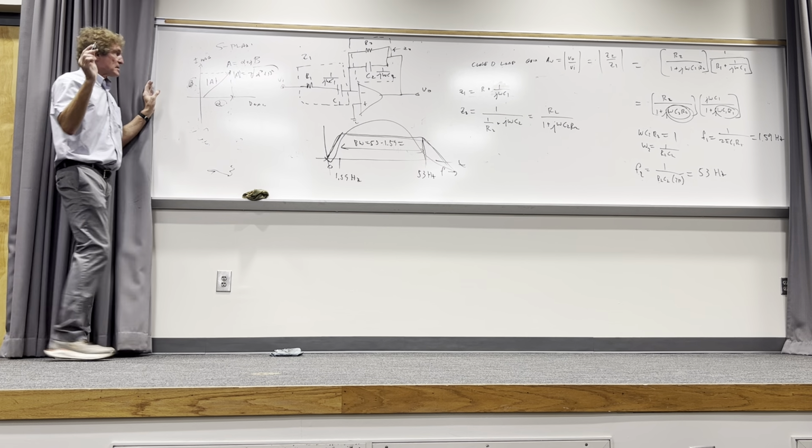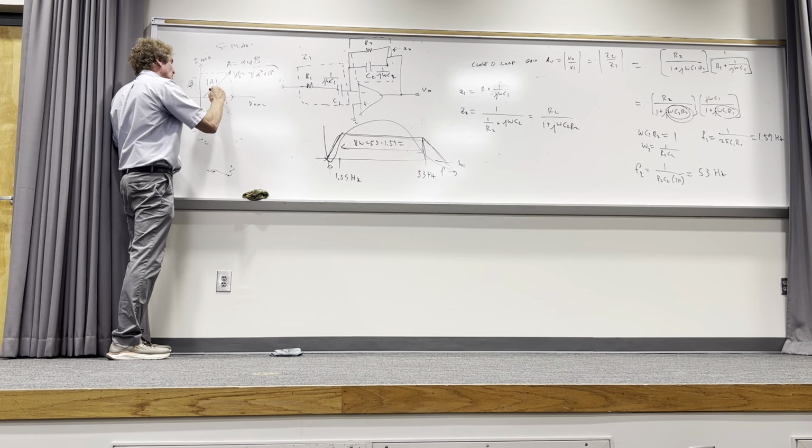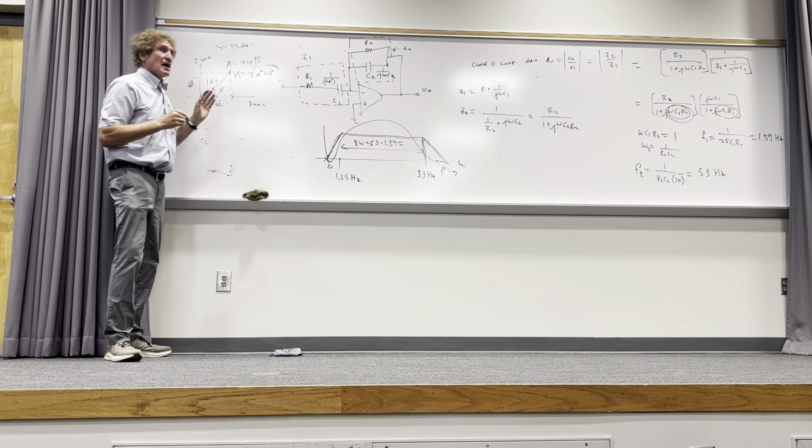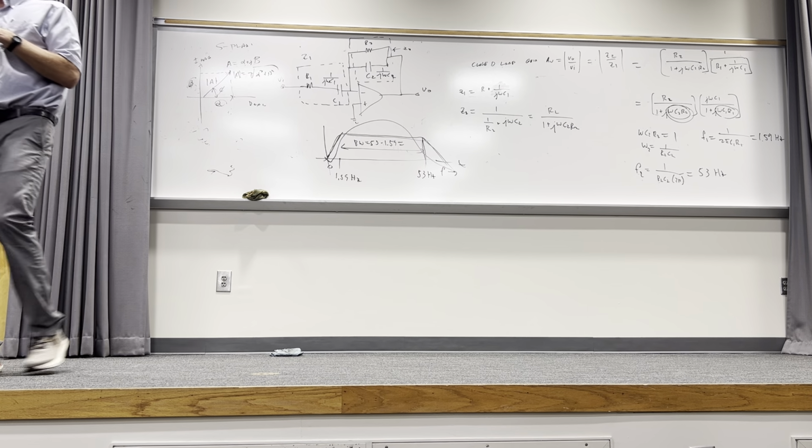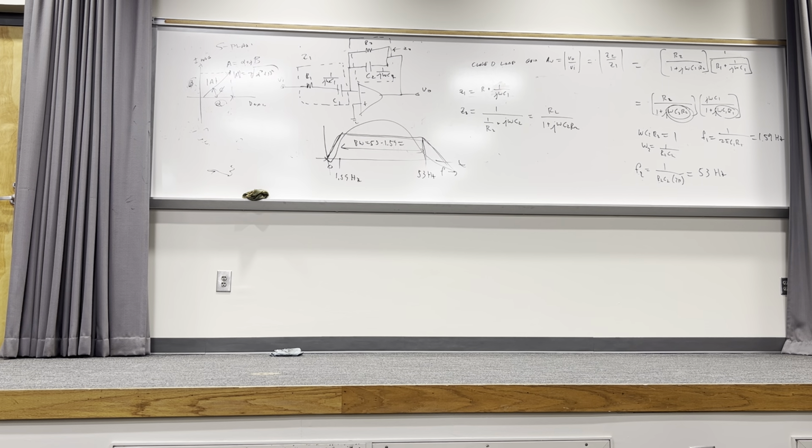All right, how do you get the angle? Let me ask this for everybody's sake. If this angle is phi, how would you as engineers get that angle? A tangent would work, a cosine, a sine; you've got all three sides of a right triangle. Opposite over adjacent is equal to the tangent of that angle, so inverse tan of opposite over adjacent gives you that angle. In polar form, you get magnitude and angle. In rectangular form, you get real and imaginary. Did that answer your question?